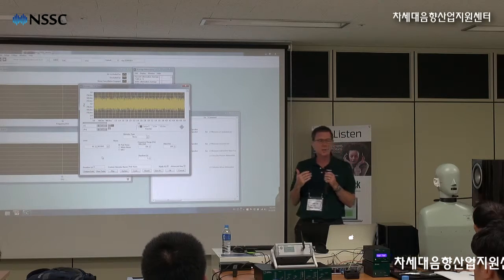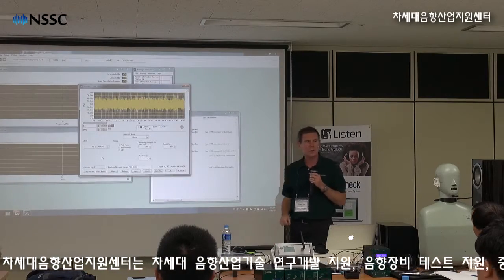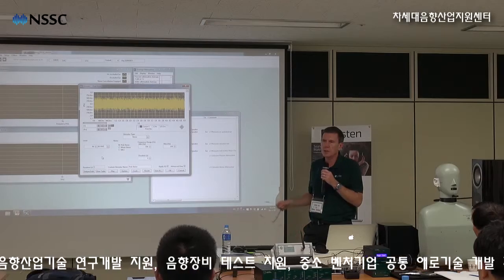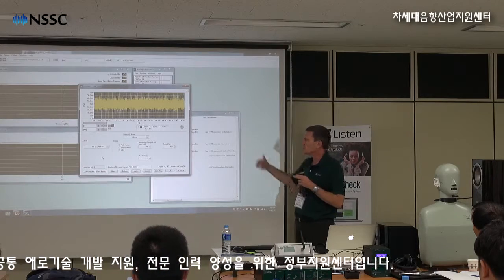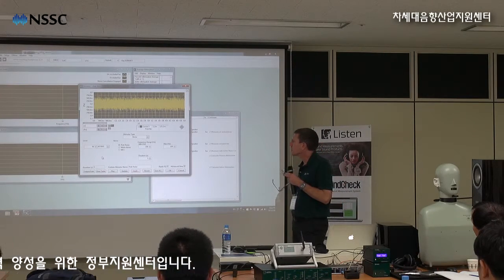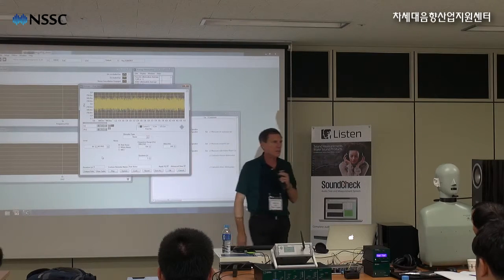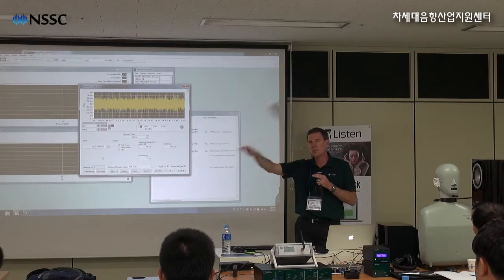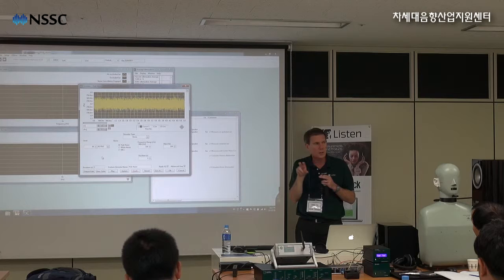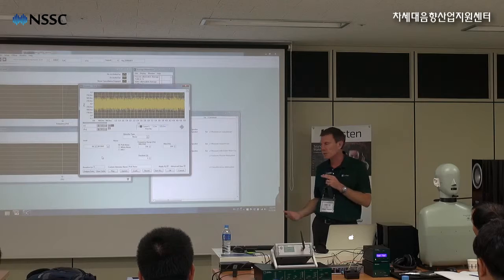Now it is possible that especially the active noise cancellation circuit will change its effectiveness with level, because quite frankly, at higher levels, it needs more amplification to cancel. So it is a good idea to try doing it at different test levels. And for today, I'm just going to measure from 10 kilohertz to 100 hertz. It depends on the loudspeaker, how low in frequency it can go, because I'm equalizing it. I want to measure at a constant sound pressure level, so if I have a little loudspeaker up here and I try to tell it to output 90 dB at 20 hertz, I'll probably blow up the loudspeaker. So we don't want to do that.